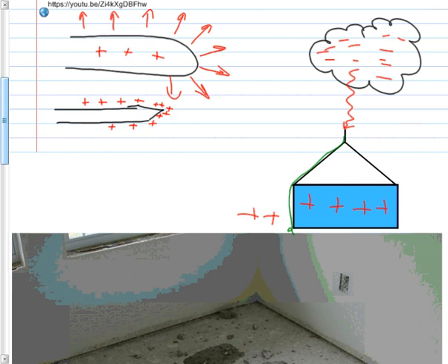So what is the purpose of a lightning rod? Well, there's actually a dual purpose to that lightning rod. One is, if the buildup gets strong enough that it discharges, and it's called a lightning bolt, then we would like it to strike that lightning rod, which will have a nice copper cable that runs down into the ground. So a lightning rod is not just a rod isolated sitting up there. It is connected by a wire to the ground. And so it provides a path for the electricity to follow so that it doesn't go through my house and catch my house on fire or blow a hole in my house or something like that. That's one purpose of a lightning rod.